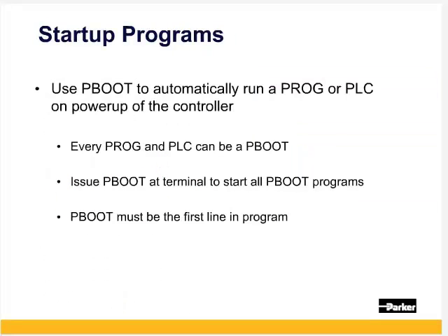To have a program run automatically on PowerUp, use the PBOOT command. This must be the first line within a program. Any or all programs and PLC programs can be a PBOOT. Issuing PBOOT from the terminal window will start all PBOOT programs.